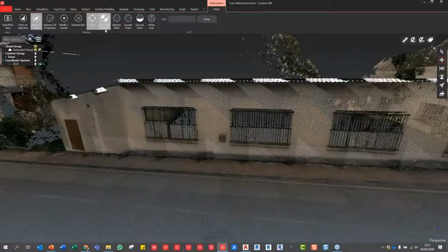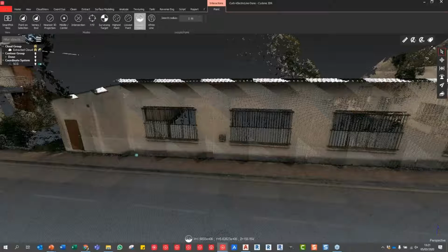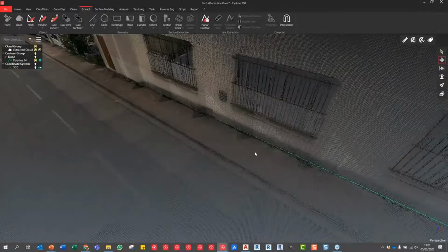So one thing we can do, let's flick our point cloud. Oops, excuse me, let's cancel that out. Oh, that was it. I wanted to show you the ability to use the ground point selection when drawing and digitizing a polyline. I've selected the polyline tool in this example, and as I'm moving along the building, can you see the blue line moving across the bottom? Even if I pick at the top, as I pick along the top of this building, and hit return, I'm going to escape out of this function, but that polyline has been created down that bottom end.